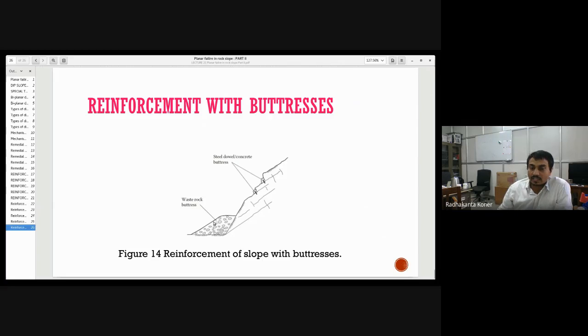So that wall basically is giving a horizontal thrust force on the slope, and the slope will remain stable. And they have designed this wall in such a way that the wall is going to accommodate that amount of pressure developed on the slope, and the shear force developed on the slope, that it will accommodate, and the slope will remain stable at this position. So this is all about the special kind of planar failure mode and its associated concept